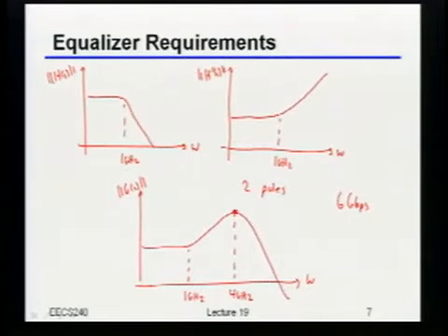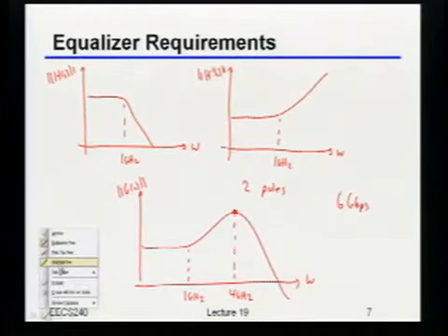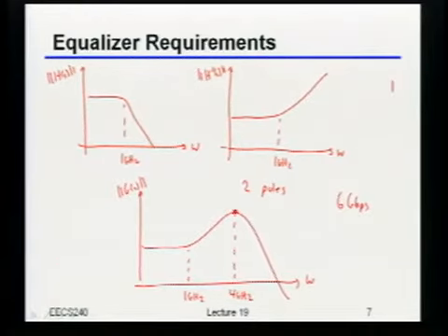The other pole has to do with the fact that no matter what network you build that creates this zero, you can never get infinite gain at high frequencies. So anytime you create a zero in a real circuit, it always has a pole associated with it too. Now, I've just assumed that both of those poles are sitting right there at the same spot.